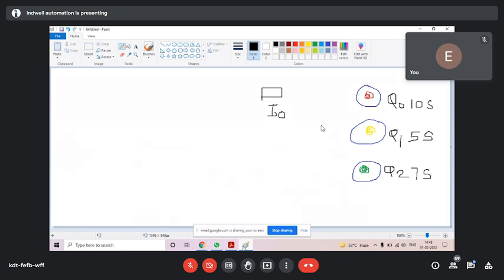That is a push button. The switch is push buttons. Once only I have to press. Press I0 once, like previous example. Press a start push button. Q0 should be on for 10 seconds. After 10 seconds, Q0 off, Q1 on for 5 seconds. After 5 seconds, Q1 off, Q2 on for 7 seconds. Make it please.